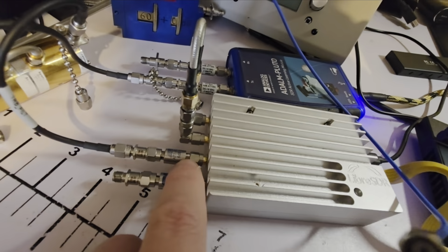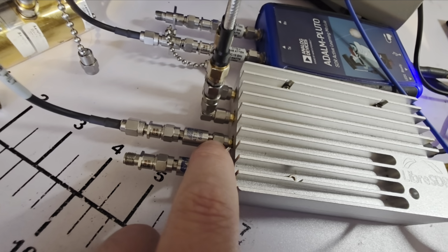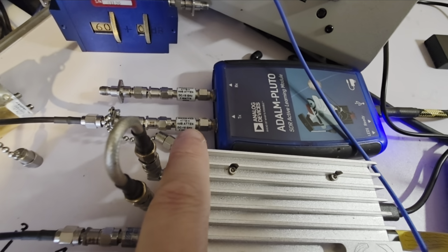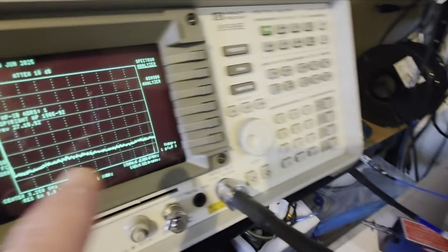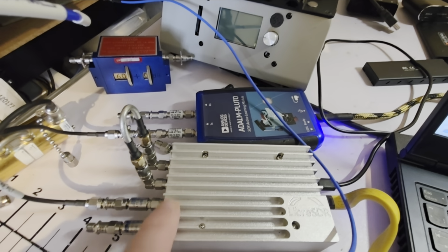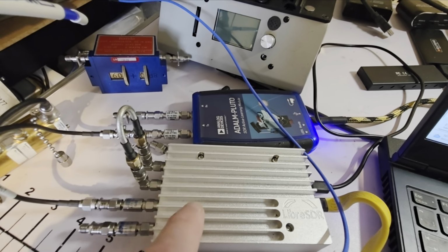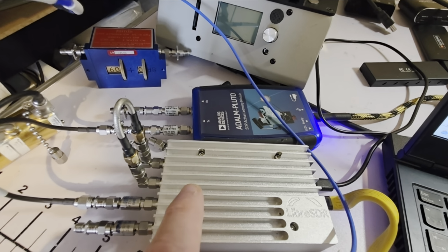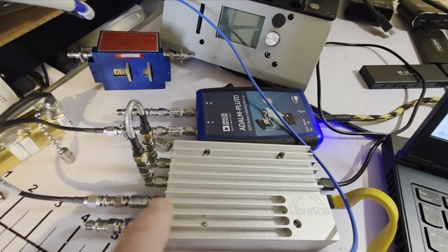I already have 10 because I have a 6 dB and a 4 dB attenuator, so they started at 10. The same does the spectrum analyzer. It's for impedance matching. I don't know exactly how that works, but when you do this, you should have, if you can, 10 decibels in pads in attenuators. First is better.